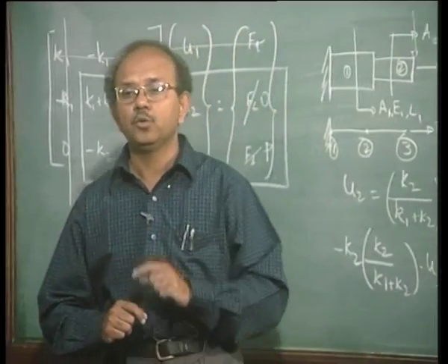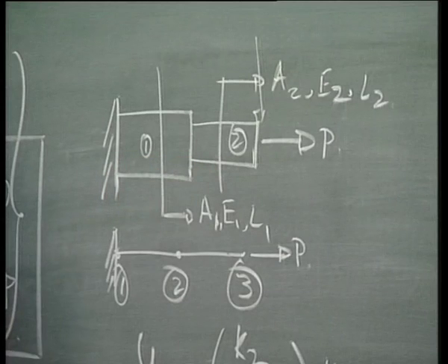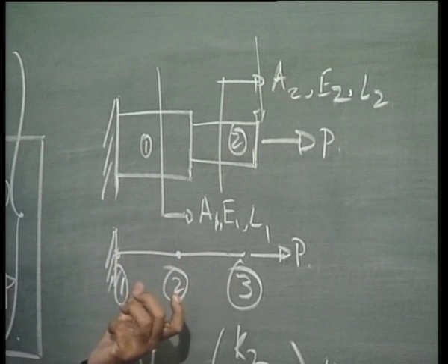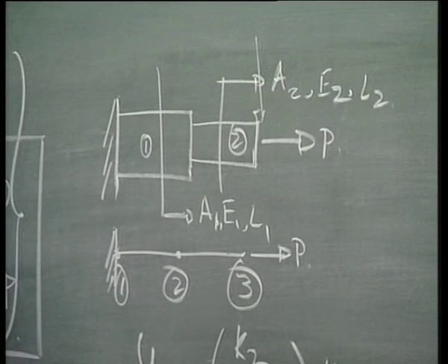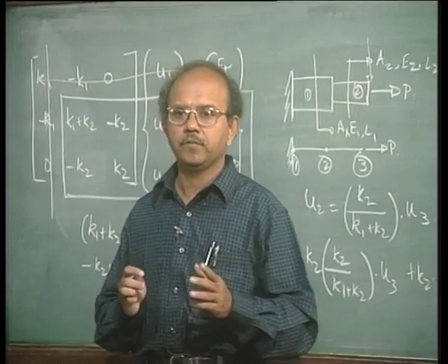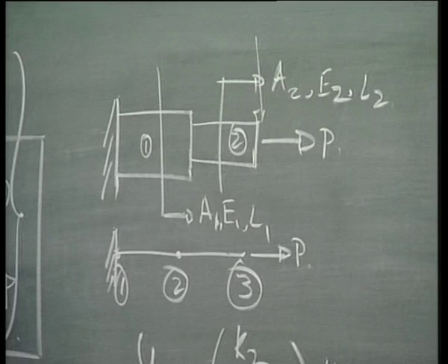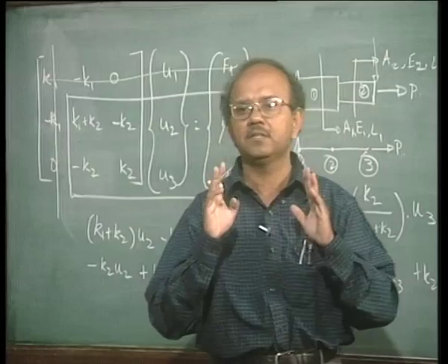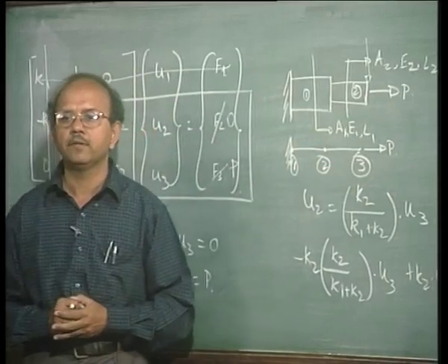So, after having realized this, you also felt that if I divide this into two elements, it is nice, because this guy has one area, this guy has another area. So, I can have two elements, so that my calculation of stiffness matrix does not become very messy. Is that clear? So, you chose this element, again looking at geometry and having a knowledge of the stiffness determination. So, that is the second step you did, you discretized it.